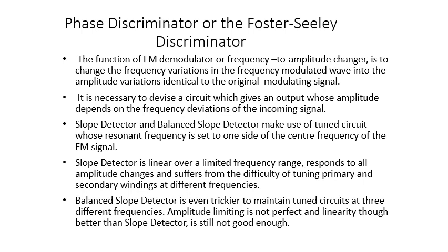The meaning of S-shaped frequency response is that the output voltage of the circuit is directly proportional to the frequency of the incoming signal. So we can say that in slope detector or balanced slope detector or the phase discriminator, the output frequency response is S-shaped. This is the basic concept.